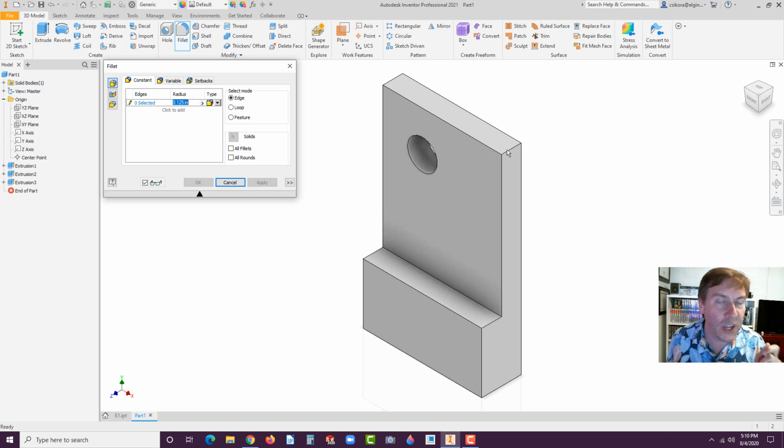Now what you do is you tap the edge where you would hit it with a file if you were filing it down. So click on this edge right here. Oops, I have to click in this little box here because I was tinkering inside there. So I'm going to click on this edge. Now I see a little preview and there's a drag handle. Go ahead and grab it, push it in. Okay, so you can actually get, and it tells you over here the feedback, like get it to 1 inch or click in there and type in 1 inch.